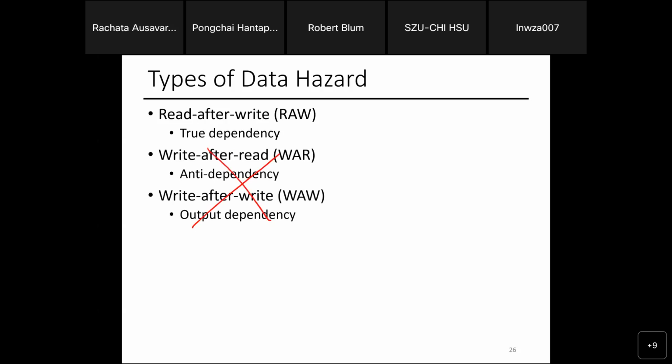But every single CPU that you own will run into these 2 problems, because your CPU, when you have instruction 1, 2, 3, 4, 5, 6, in theory, you're supposed to do 1, then 2, then 3, then 4, then 5, then 6, right? And let's say this is a memory instruction that takes 200 nanoseconds. It takes a long time. It means that I have to wait for 3 to finish before I can move on to 4, 5, and 6.